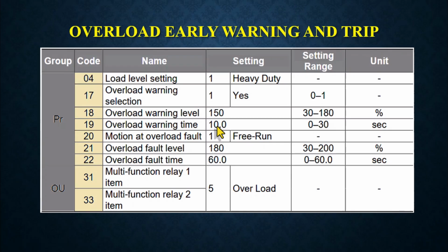For example, if you set it to 150%, and if for 10 seconds 150% of the rated current that you specified in base 13 is drawn from the electric motor, the inverter detects that now it should issue the overload warning. So that's about its overload warning.